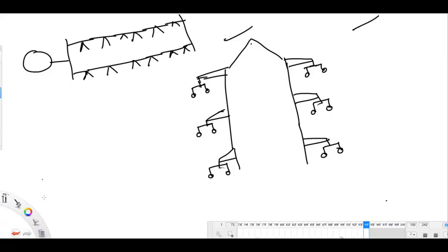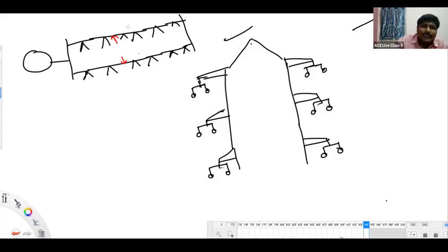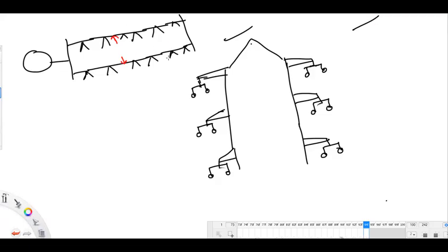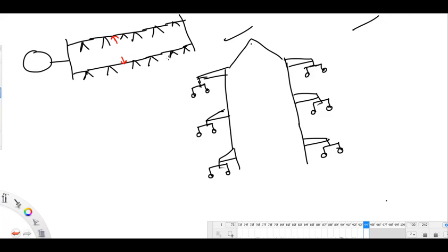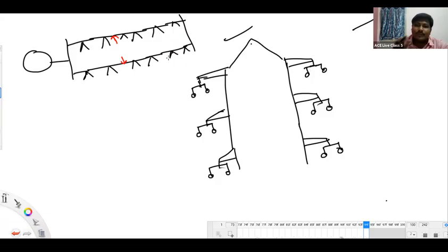And the distance between these two lines is very, very high, so we can neglect the mutual linkages between them. That is called a parallel line. You can ask me whether a double circuit line is also a parallel line. It is also a parallel line, but there will be mutual linkages. That is the minor difference you have to observe.